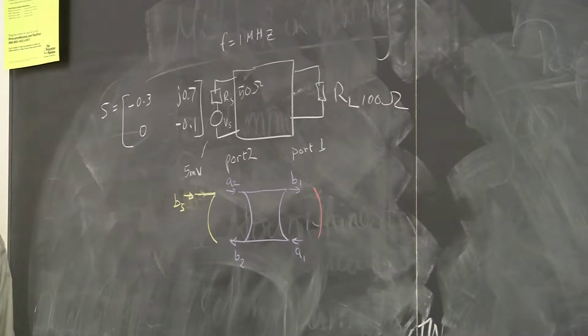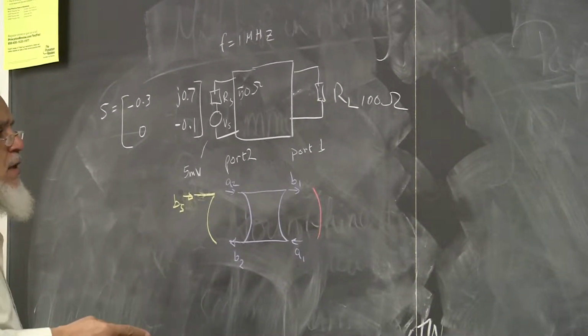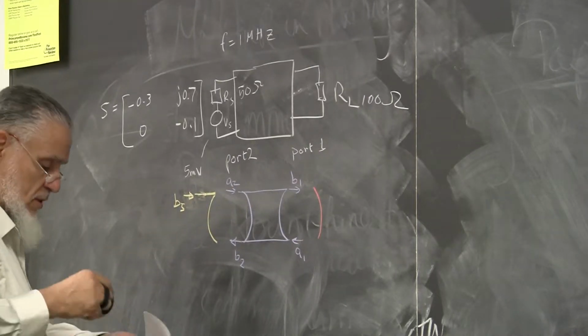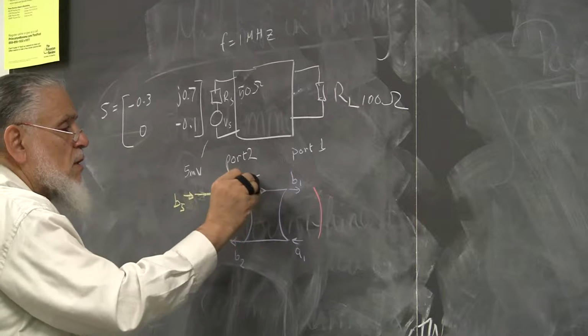Now, we have to distinguish between signals and S parameters. The signal is the power flow, while the S parameters are the ratio between signals. So the S parameters are like the gain or the attenuation, whichever way you want to look at it. It's basically gain, all right? So the ratios are the S parameters. I'm going to label those in white.